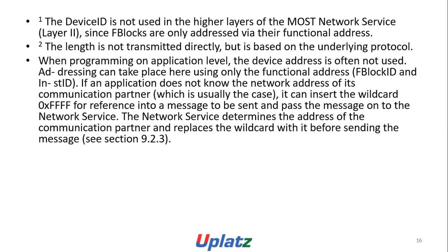The DeviceID is not used in higher layers of the MOST network service, layer 2, since Fblocks are only addressed via their functional address. The length is not transmitted directly, but is based on the underlying protocol. When programming on an application level, the device address is often not used. Addressing can take place here using only the function address: FBlockID and InstID.